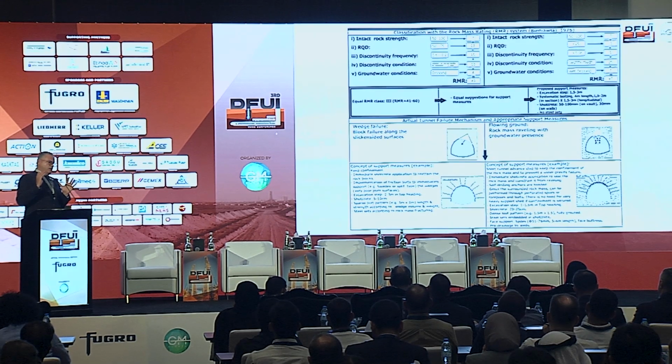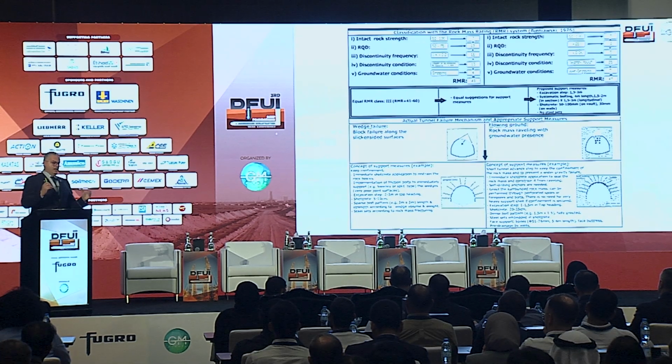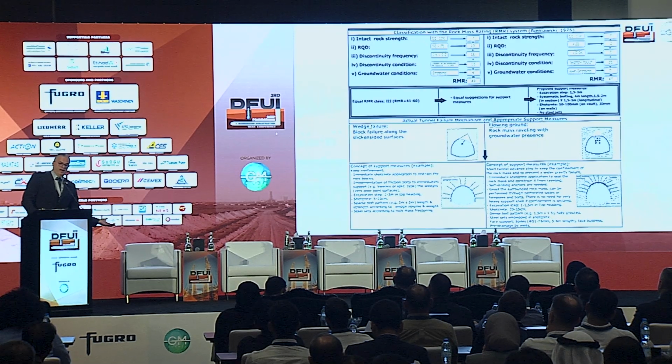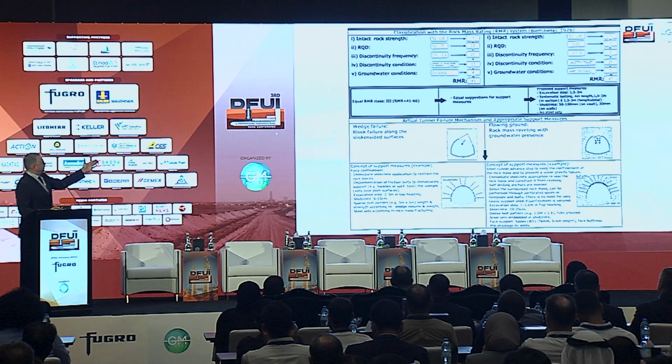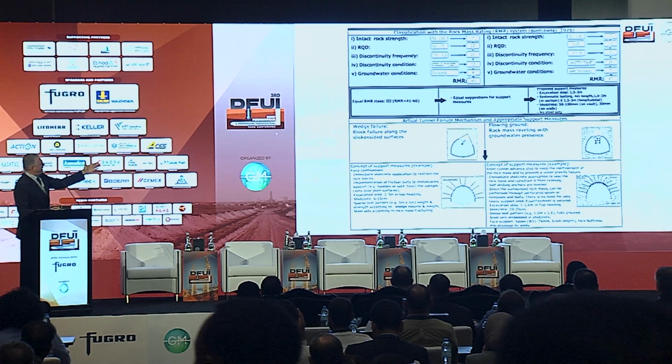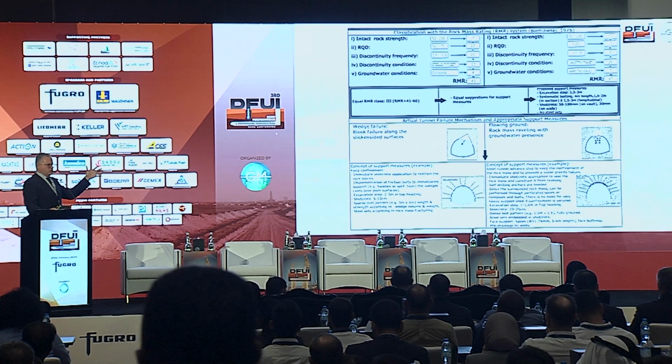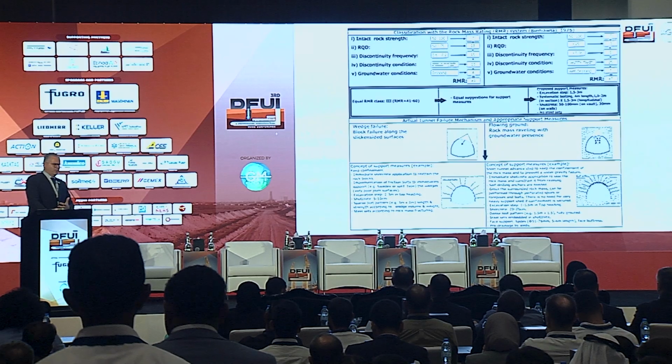So yes, they help us characterize this rock mass and help us identify, after excavation, how we can communicate to the designer, to the owner, to the contractor, how our rock is. But putting that into every kind of analysis, we need to think about the behavior. So in one case, we have structurally controlled wedge failure. On the other hand, we have raveling ground or flowing ground. So the support philosophy is completely different.